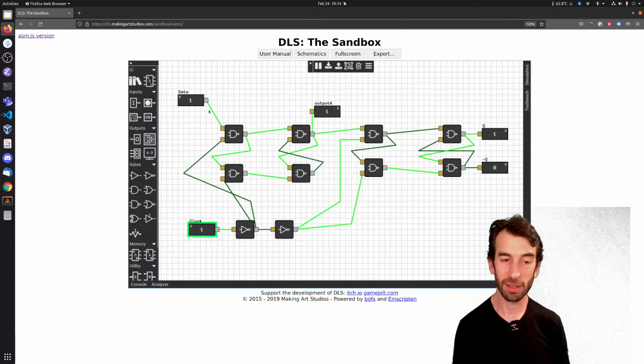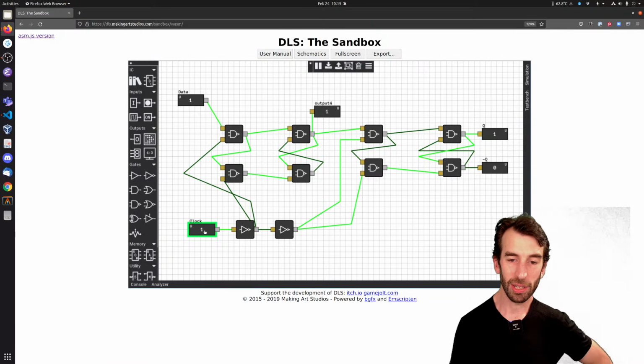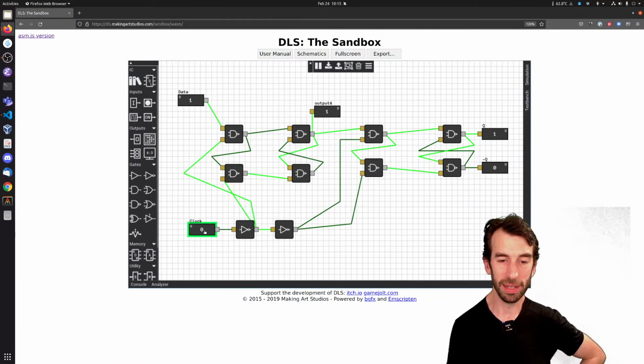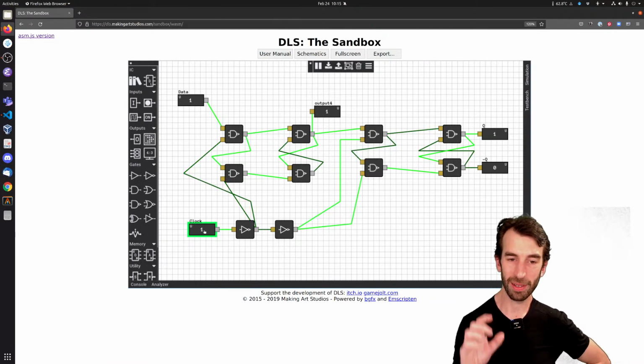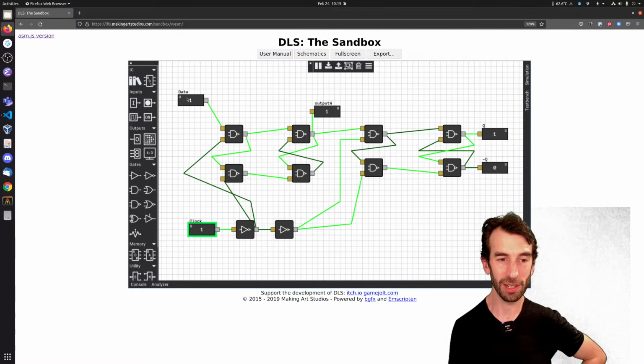So that means that this JK design, as the clock goes 0, 1, 0, 1, takes an input at the 0 stage, stores it inside, and then when it gets back to the 1 stage, it comes out. So here we're at 1, so the output is being displayed. We change to a 0, store the input, change to 1, and it ends up on the output.